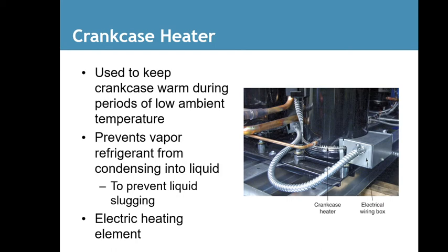It's not in the sealed system. It doesn't make its way into the inside system where there's oil and refrigerant. This is just a little tube that they built onto the compressor body, and this little round heater slid in there. Somewhere between the size of half a roll of nickels and half a roll of quarters. It slides in there. There's 2 wires on it.